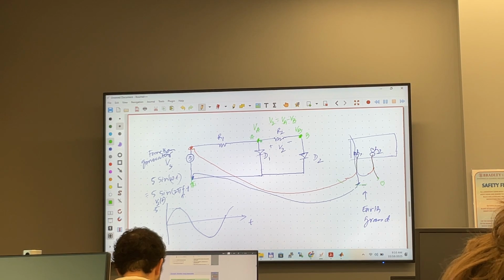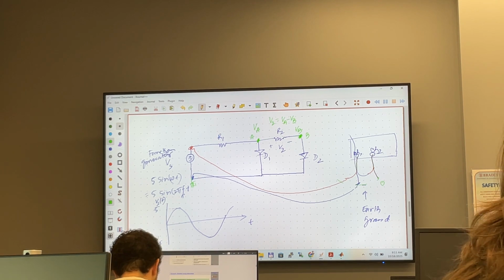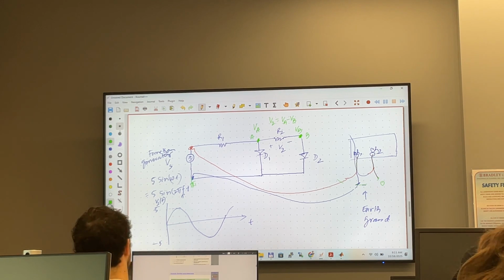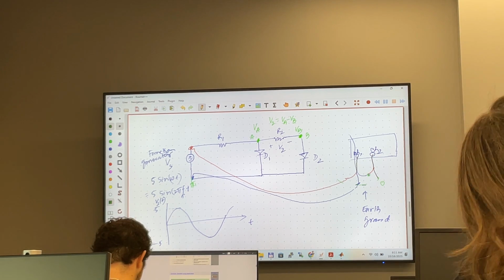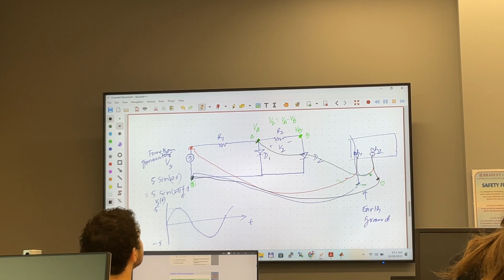You subtract this node voltage minus this 0, and that is going to be this voltage. Okay? But if you want to take the voltage across any other resistor or any other component between two terminals, it's basically a differential voltage. You always keep that in mind. So for that, you take a node voltage using channel 2. You connect the channel 2 positive terminal right here, and the channel 2 negative terminal you connect right here.